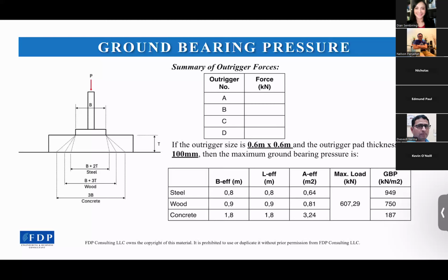But you need to check the steel mat itself, because there will be bending or punching on the steel mat. That is why we are going to use a thick mat, to avoid that punching. Yes, if there is bending on the plate, then it will not be normal pressure anymore. So you need to consider the bending of the mat itself. Okay, thank you. Yes, no problem.